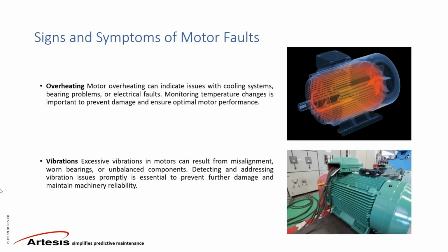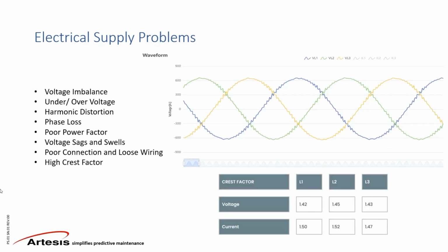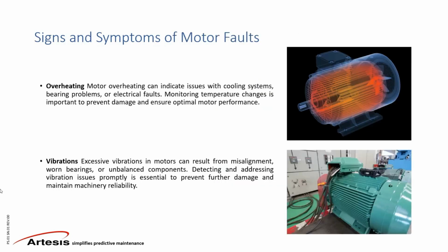And when, of course, you have issues in any of these factors, they will show themselves with different signs and symptoms. And overheating will be the first one, because, again, inefficiency means more heat dissipation inside the motor. And mechanical problems will, of course, manifest themselves as vibrations.